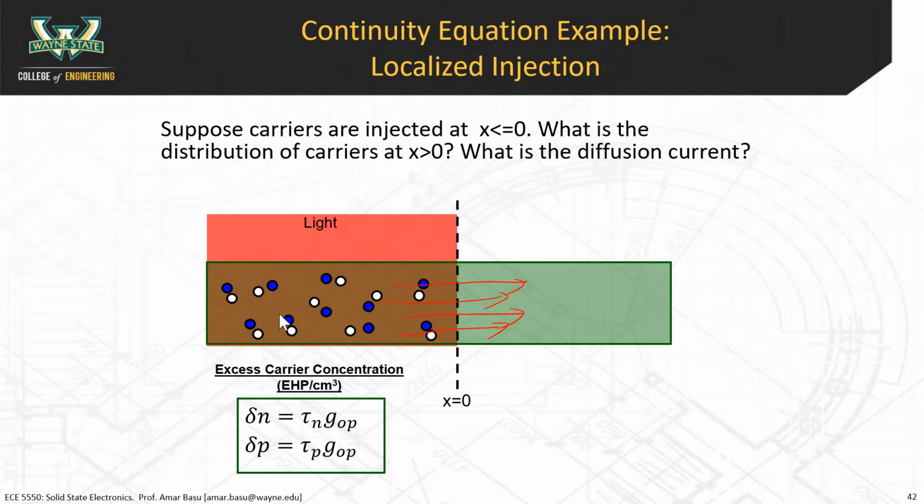Electron hole pairs. Electron sees another hole, they recombine, right? So what's going to impact recombination? Higher carrier concentration, right? So the fact that we have excess carrier concentration means that there's going to be more recombination. We shine light on the material, it increases the generation rate, and it also increases the recombination rate. Both. And they're both in equilibrium. These equations that I showed you earlier, like steady state carrier generation, apply to equilibrium when the generation and recombination processes are balanced with each other.